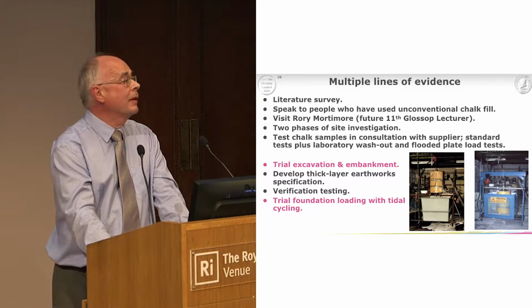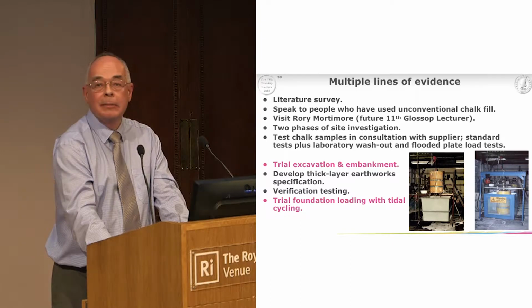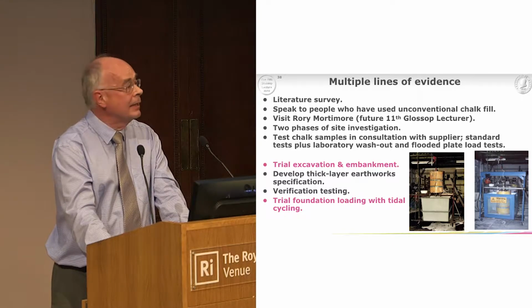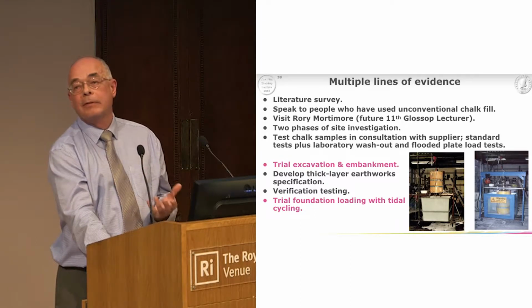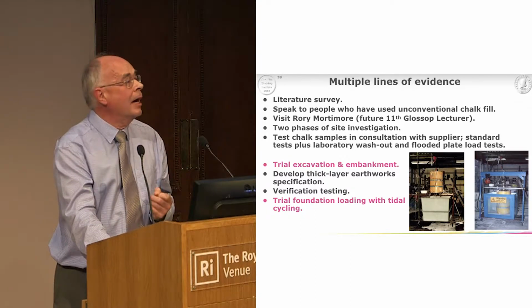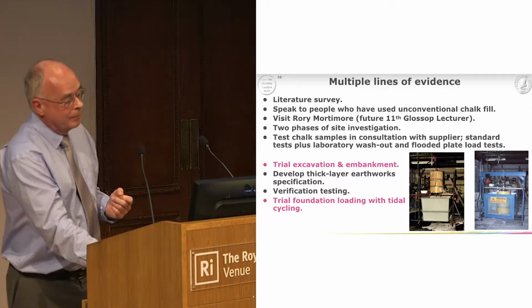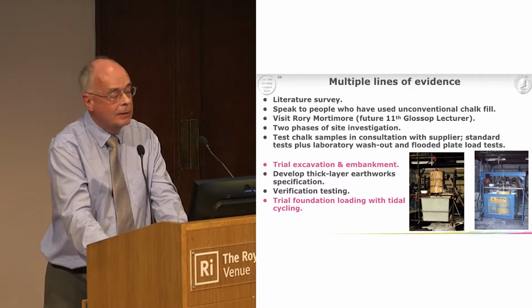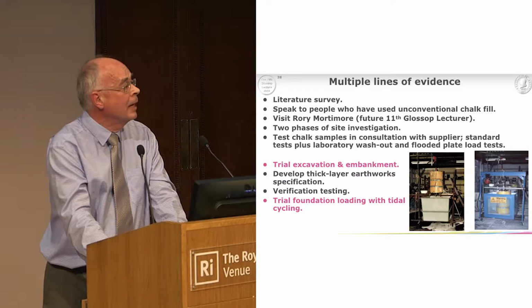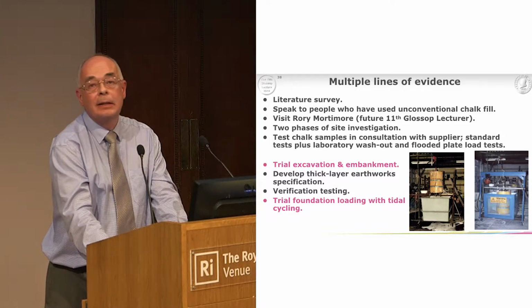Then we went out on site and did a trial excavation and embankment, and from that we developed this thick layer specification. Then we constructed it, and during construction there's an awful lot of verification testing, and that included a couple of, or several actually, trial foundation loading tests, and one of them had a tidal cycling built into it. And I'm going to talk briefly about these two in the red.